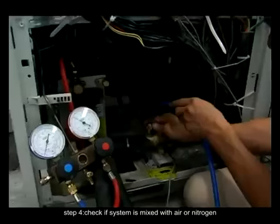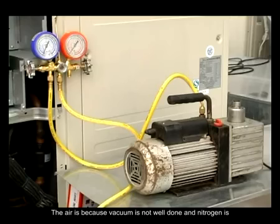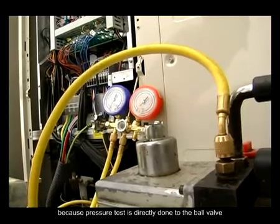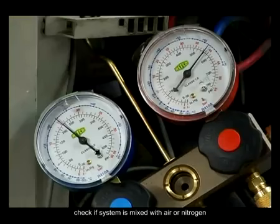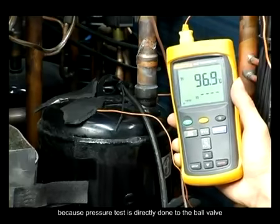Step 4. Check if system is mixed with air or nitrogen. The air is because vacuum is not well done, and nitrogen is because pressure test is directly done to the ball valve.